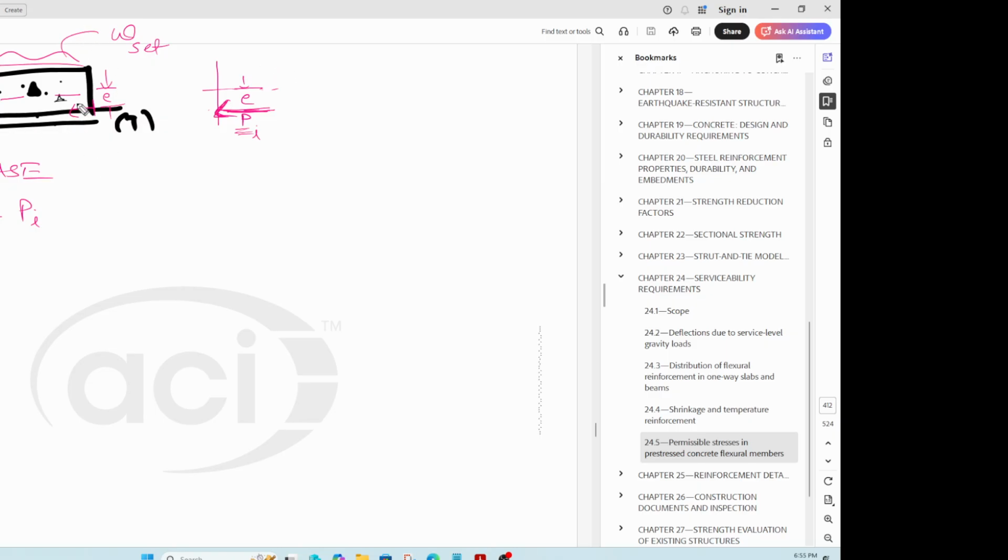So at this stage, if you try to find out the compressive and tensile stresses, you will go back to your basic mechanics, wherein I can replace this diagram firstly with a P acting at the neutral axis and a clockwise moment, P initial times e, acting like that.